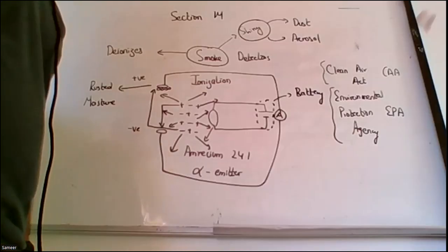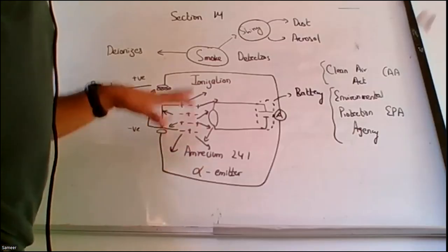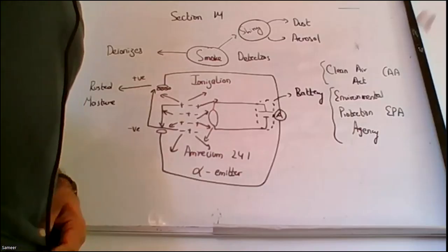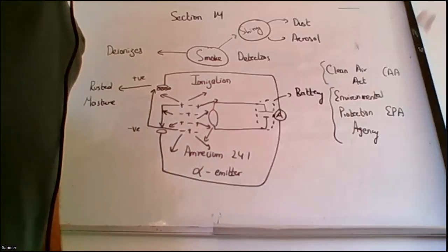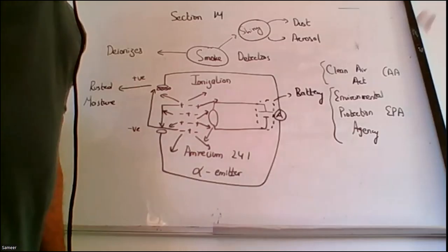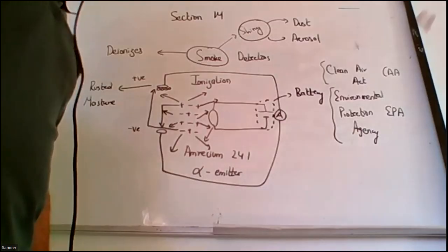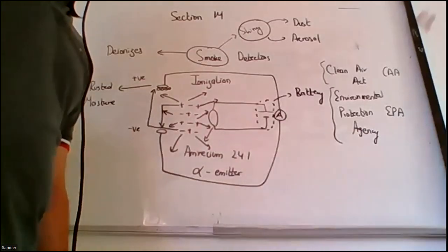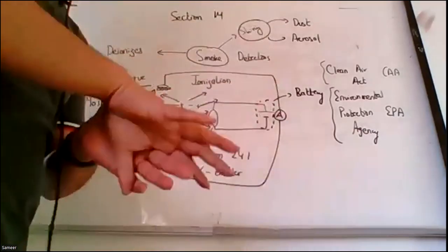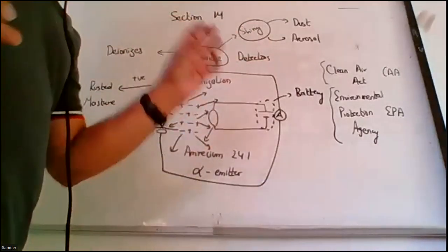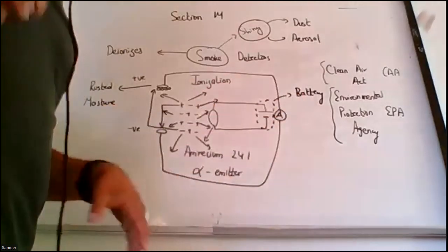The second thing, the most important parameter for the ionization detector, is the dumping. Whenever we are going to remove an ionization detector, it has a radioactive element. Most companies, when told to remove them, close them in cartons and keep them somewhere in the store. So it means a free energy source is available in the store somewhere in the cartons.